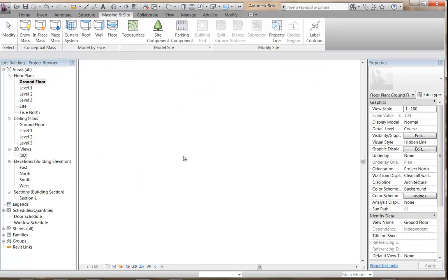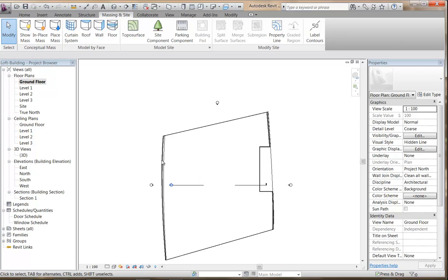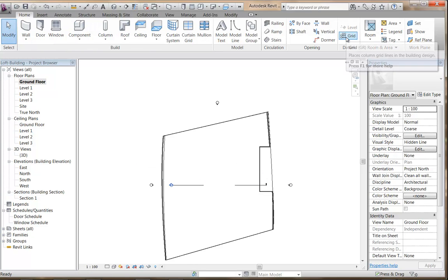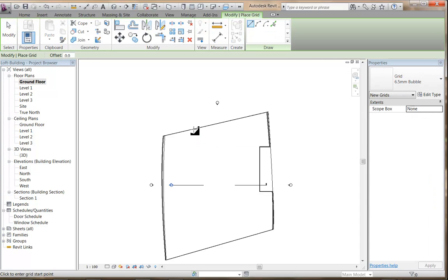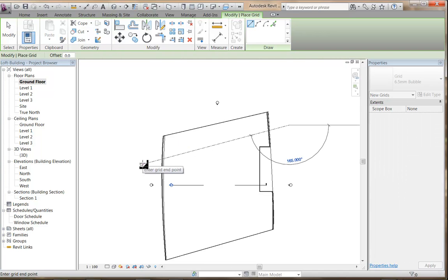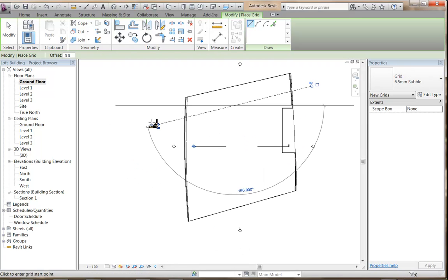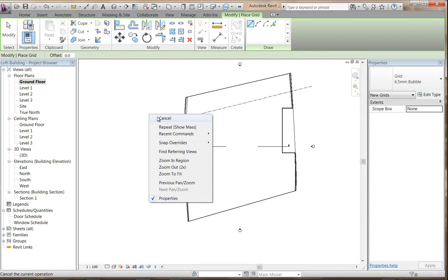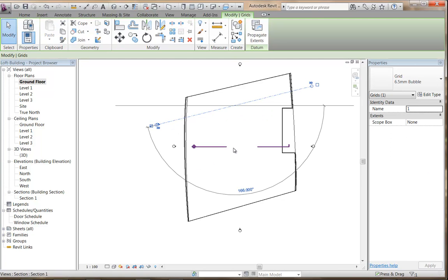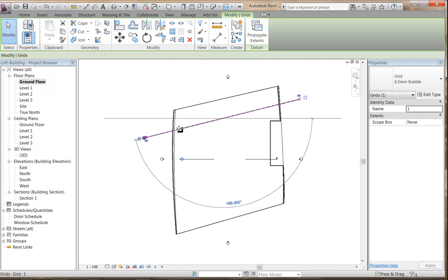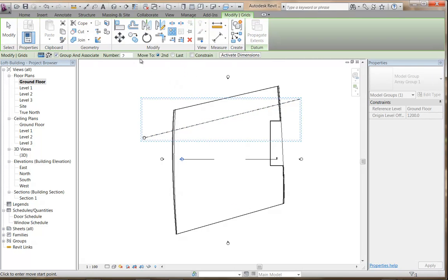What I will show you though is how to now get some interior work set up. So I'm going to put a grid in there, and you can see because of the orientation of the building, it probably makes sense to have that grid at an angle that matches the building. I mean, I don't know, I definitely want to be talking to my engineer about the logic of this, but I don't see why it wouldn't work.